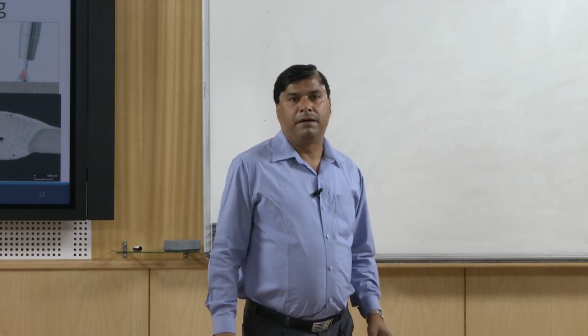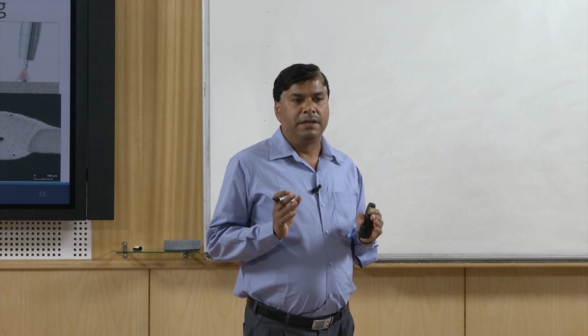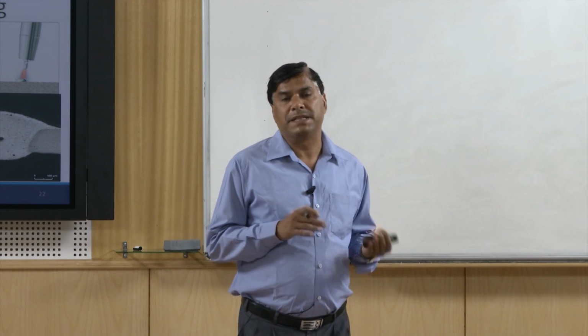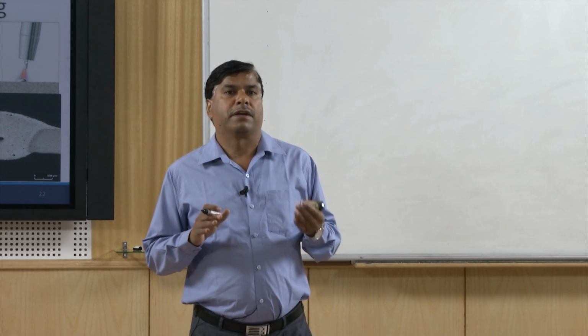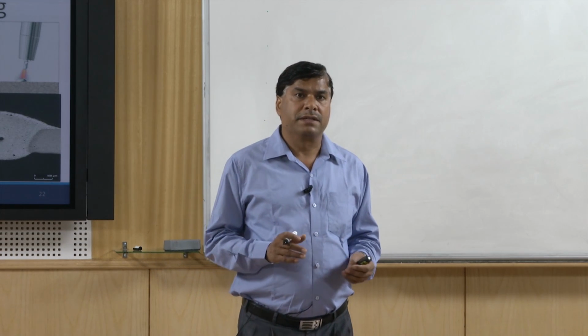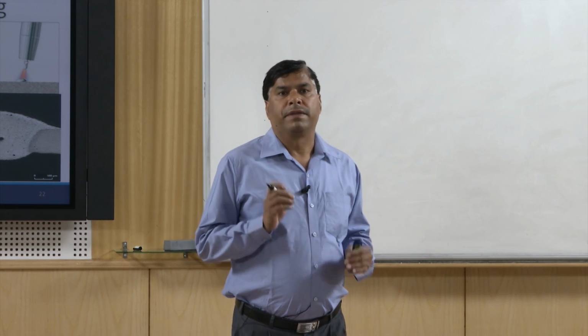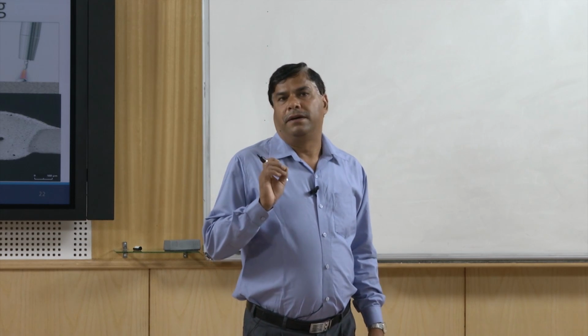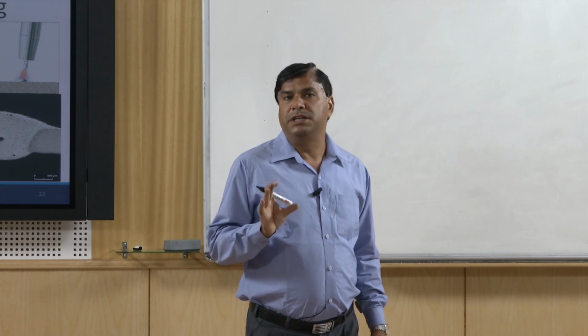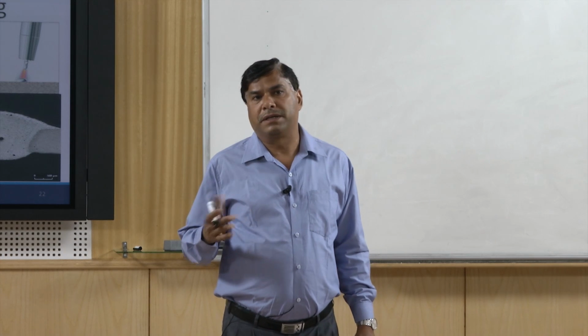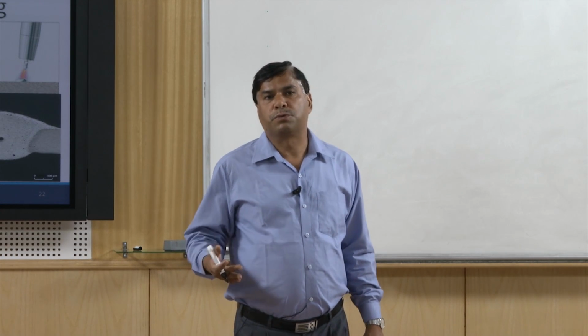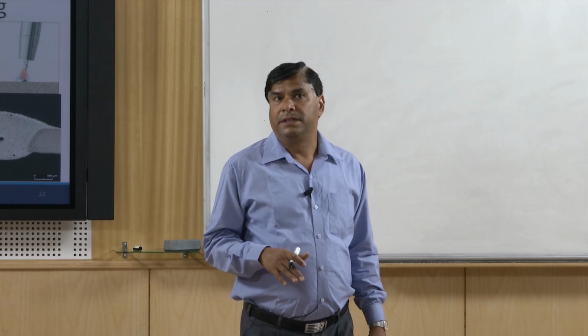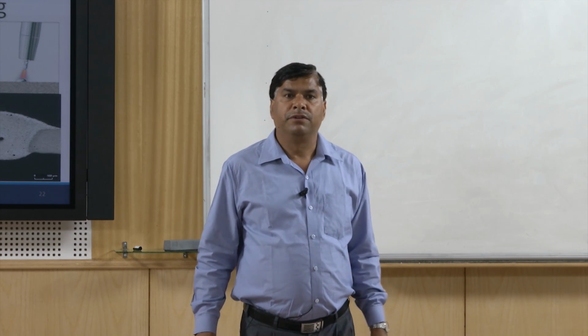In this presentation I have talked about how CMT exploits the positives of the pulse GMAW and the conventional GMAW process, and how it offers good control over the heat input and good control over the metal transfer, so that it becomes useful for joining of thin sheets. Thank you for your attention.